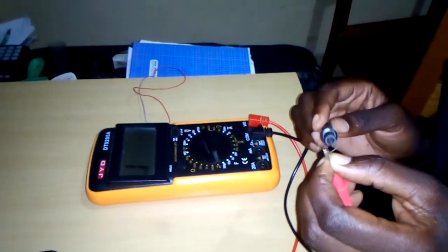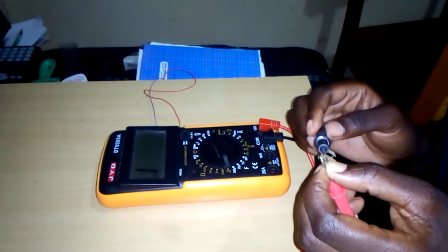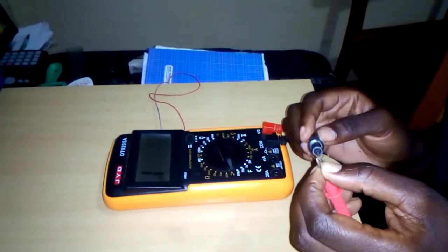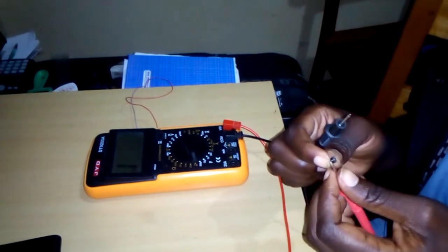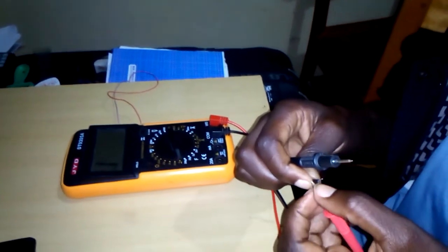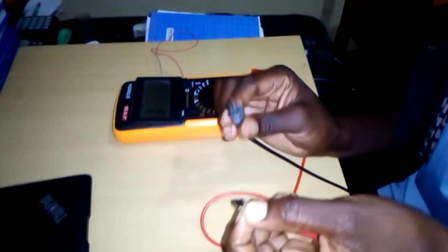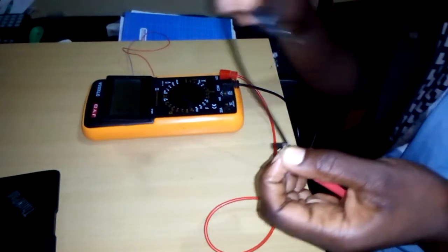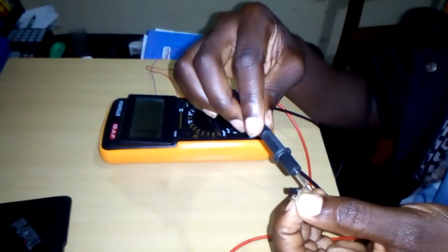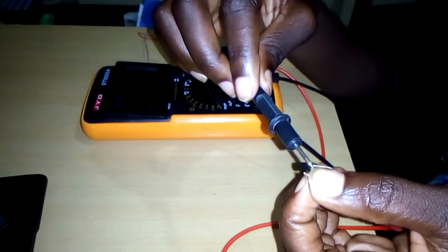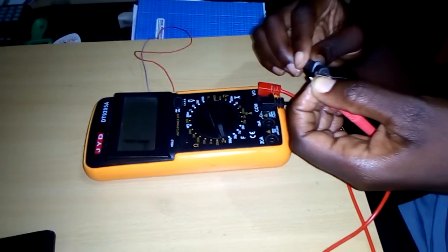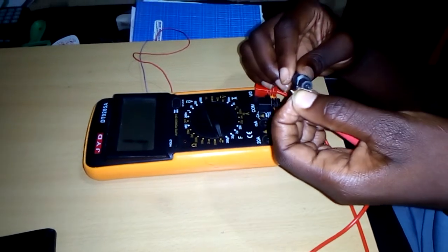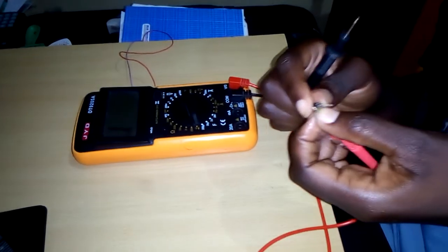as you can see. In case our multimeter does not bring any recordings, it shows that it's still on 1, so we move the red probe onto the next pin, and with that we use the common probe to test again on these two pins. As you can see on our multimeter, it's still showing that we haven't found the active base.